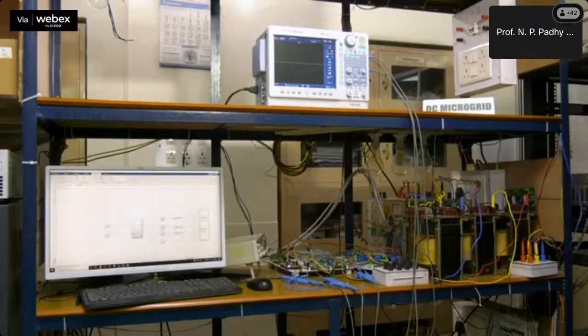In the same test bed, we demonstrated the islanded operation of a DC microgrid. In this test case, the grid is not required, so the MCB switch is in an open position. The control system of islanded operation is flashed into the DSP controller after powering up the circuit. The AC side of the IGBT stack is connected to the bulb load.